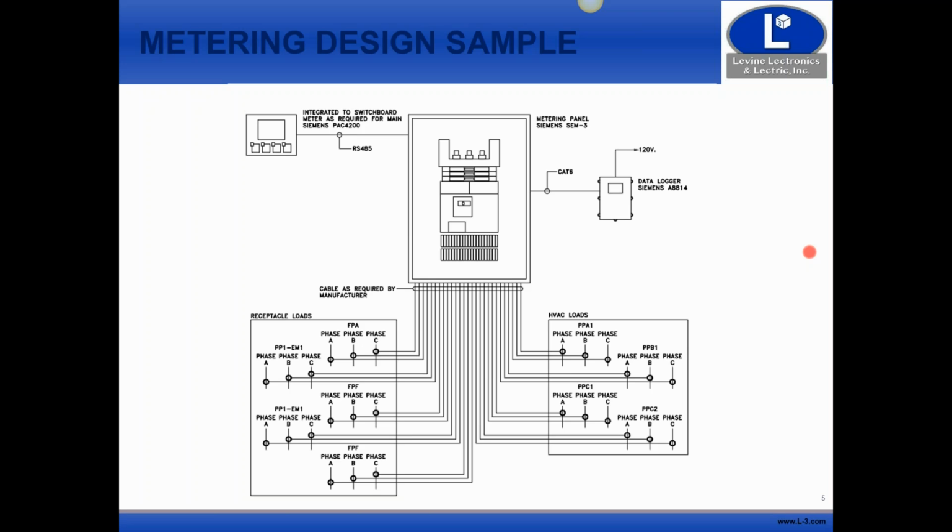In this instance, if we think about it from a practical installation standpoint, you've got electrical panels spread out all over the place in a building. You've got one circuit collection panel here that's going to be located somewhere, and now you have to find a way to run CT cabling from each panel all the way back to this location. Then it's not just putting this in either. There is a misconception of, okay, I just have to put this equipment in and we're good to go. Well, that's not the case.